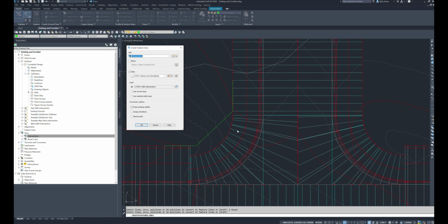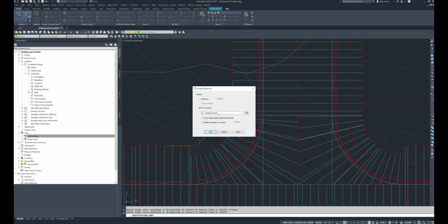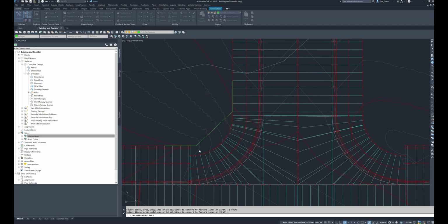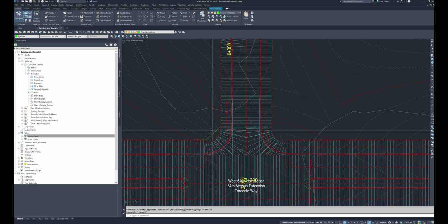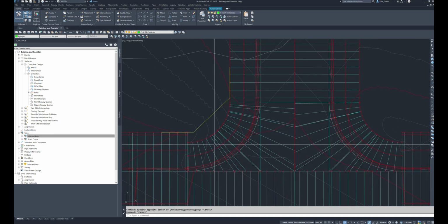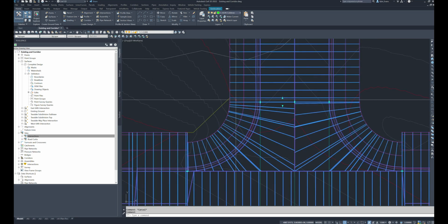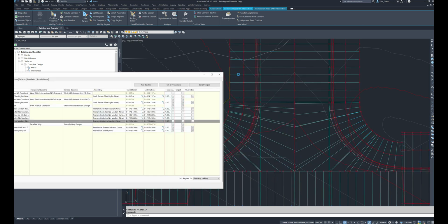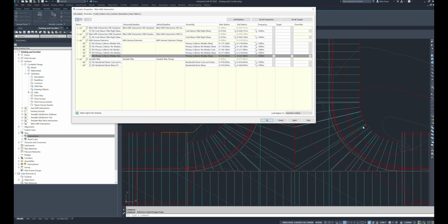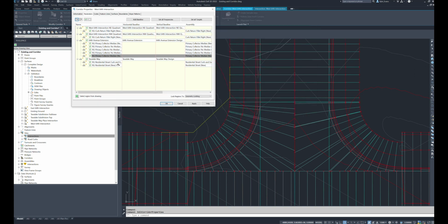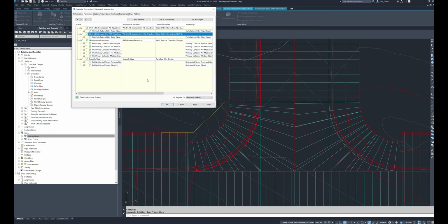I don't foresee anything overlapping here. So we're going to go to the intersection site. I'm going to make it a yellow color so we can differentiate it. And then I want to assign some elevations from my complete design. We can probably adjust the elevations of this afterward. So we're going to now go and target this feature line. So I'm going to select my corridor, right click, go back into corridor properties. Move this out of the way so I can see what I'm clicking on. And it was this one here.